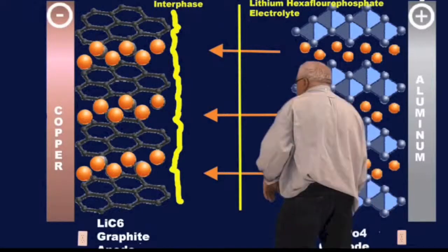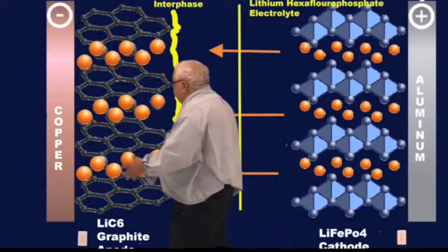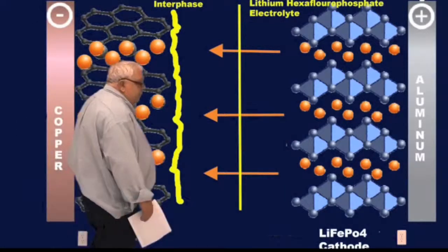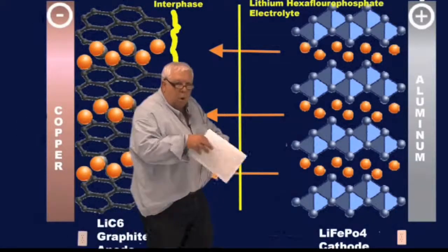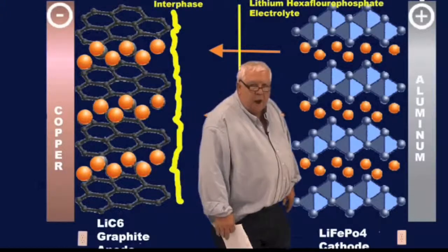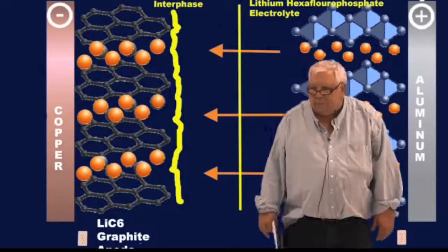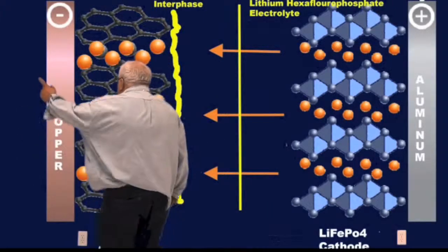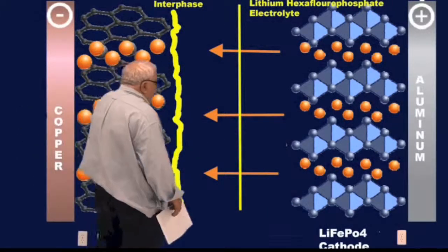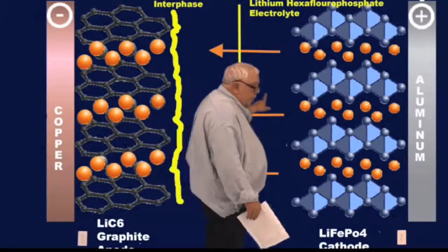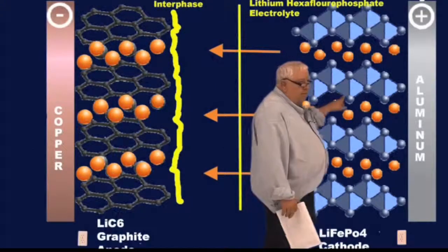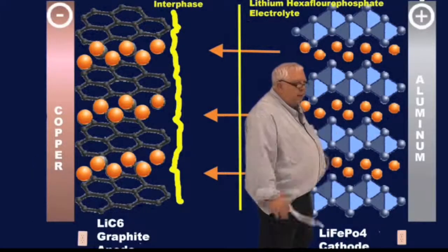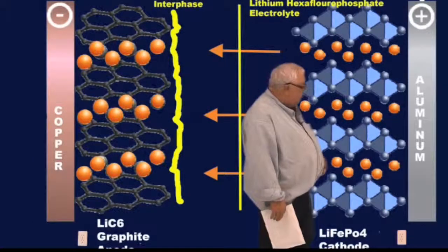When we decrease the charge here, we have essentially decreased its ability to hold all those lithium ions in position, and they begin to escape. They migrate through the SEI layer, and they migrate through the separator, which has very small holes in it. It keeps the two plates from actually touching and shorting the cell.